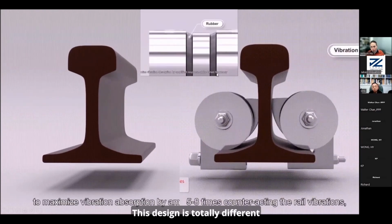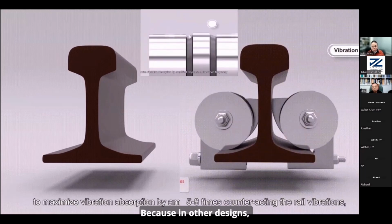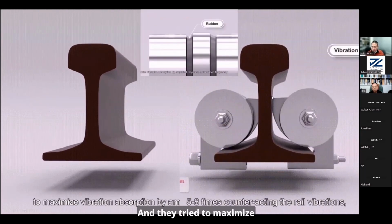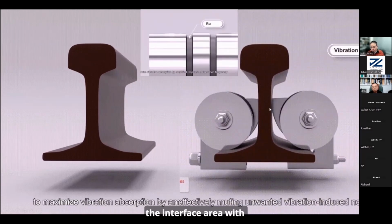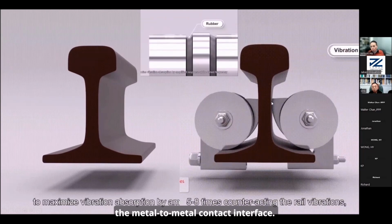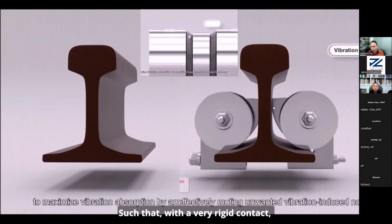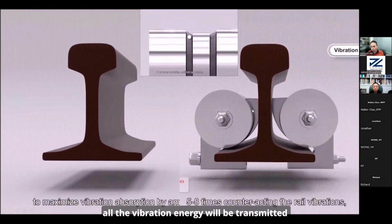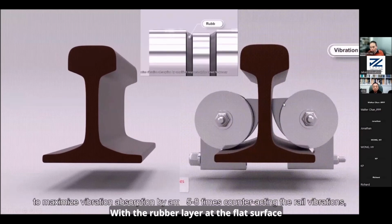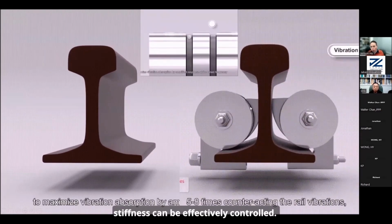This design is totally different from all the other wheel damper designs, because other wheel dampers use a rubber layer at the interface and try to maximize their interface area with the wheel. We have a metal-to-metal contact interface, such that it has a very rigid contact and all the vibration energy will be transmitted into the wheel. And with this rubber layer at the flat surface, we can very easily and effectively control the stiffness.